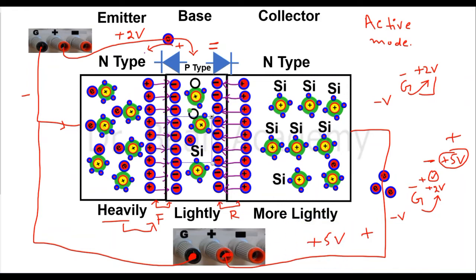And the reason that a large number of electrons would love to cross this junction instead of recombination. I told you that if recombination occurs, if an electron, when it enters the base, goes to fill the hole, once it fills the hole, then it will not be able to go through the junction. In fact, it will go to another hole, and then these electrons will constitute the current from the base. So we will see a current out of the base in this situation, and this current should be very small, and we will see a large current out of the collector. Every time we see a little current from the base, we will see a huge current from the collector.